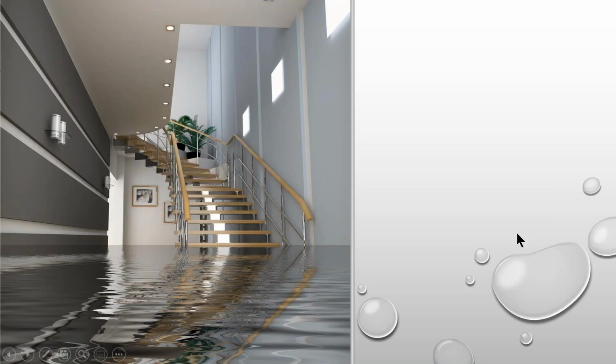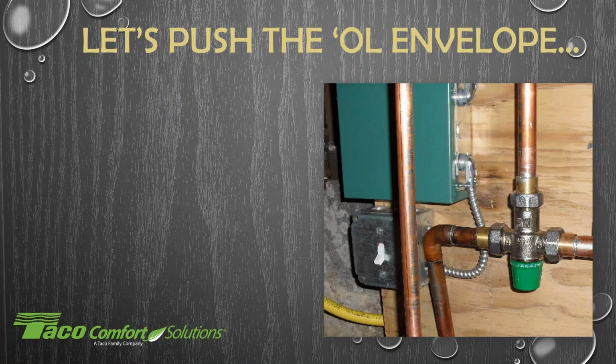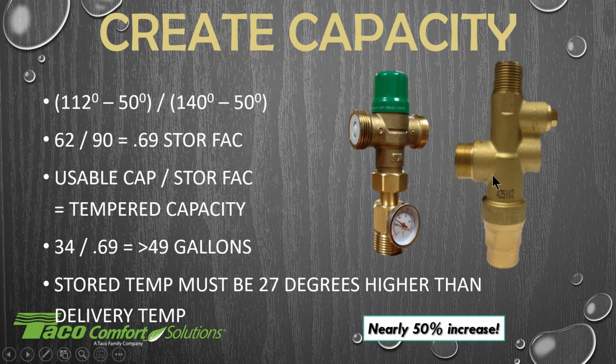I'm going to go back a slide and show you the mixing valve here on the right-hand side. The one on the right-hand side is our direct water heater mount. Which means right here at the bottom would be directly mounted to the water heater, which would see the 160. The left-hand side, this threaded portion, would be my cold water supply coming in.